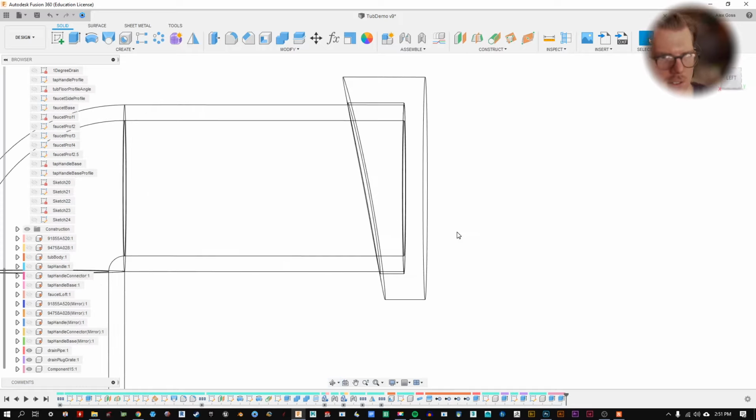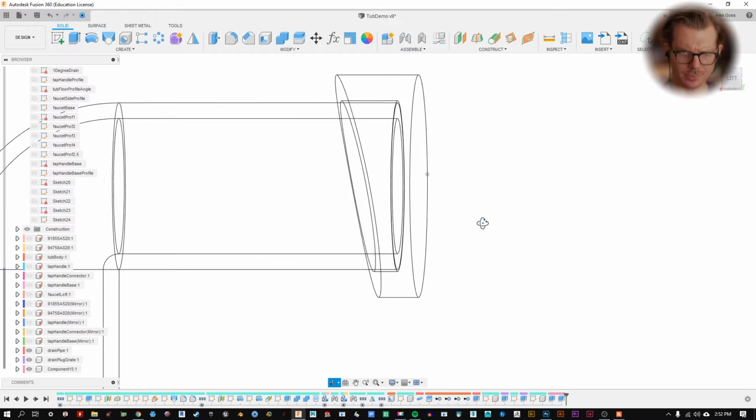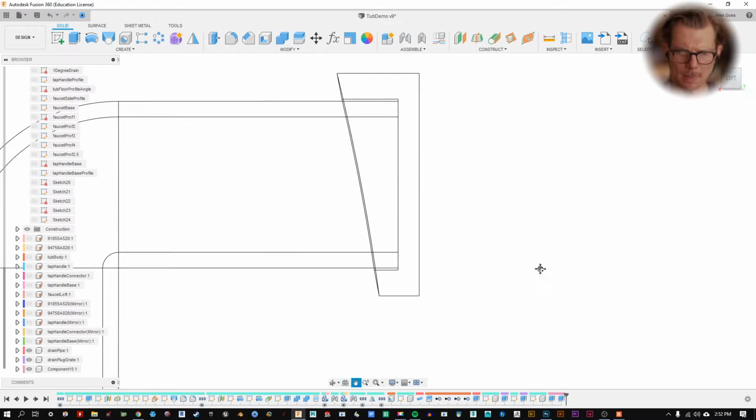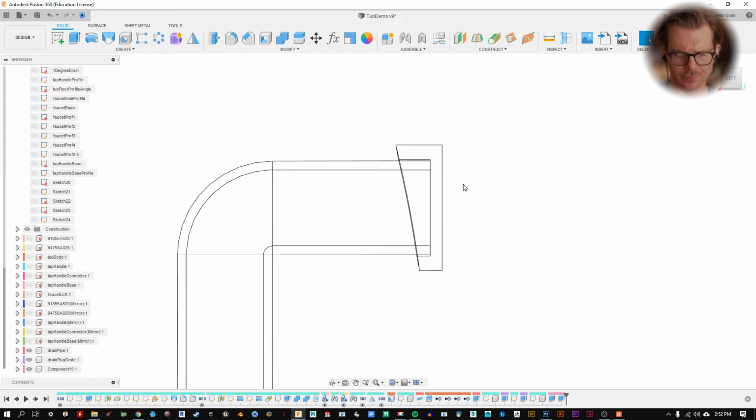If we look at this piece, it's got a slit, or a slot rather, that goes all the way through the bottom so that when water comes up, it'll flow up into here and go through the pipe. It's about all the way up, maybe a third of the diameter of that cap. So we want to end up cutting a slit up here. We could draw it here and send it through. I want to use that midplane.